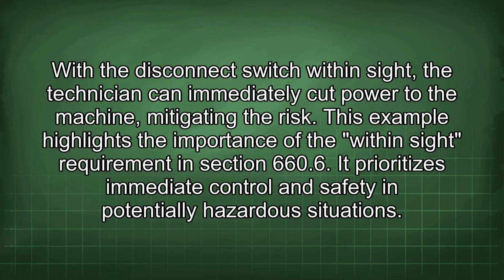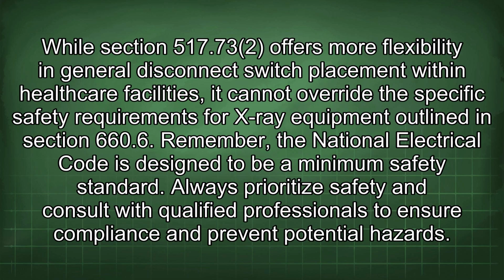This example highlights the importance of the within sight requirement in Section 660.6. It prioritizes immediate control and safety in potentially hazardous situations. While Section 517.73 offers more flexibility in general disconnect switch placement within healthcare facilities, it cannot override the specific safety requirements for X-ray equipment outlined in Section 660.6.